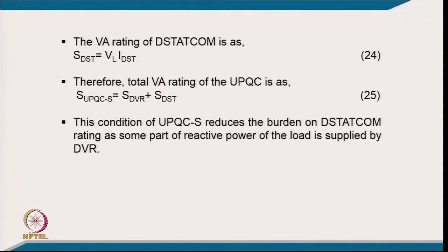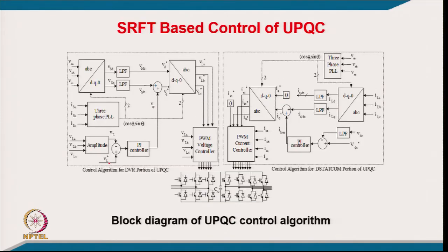So, this condition of the UPQC reduces the burden on the D-STATCOM rating, as some part of the reactive power of the load is supplied by the DVR as the angle is shifted.